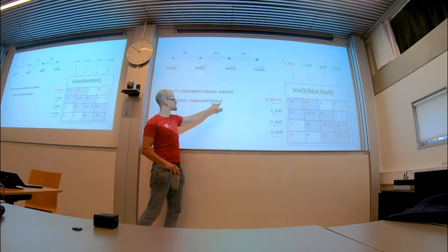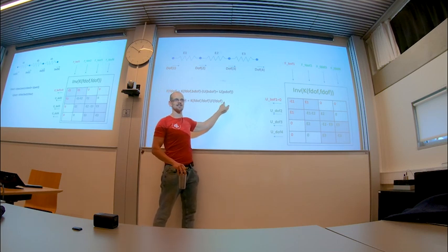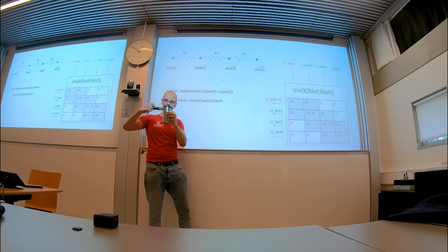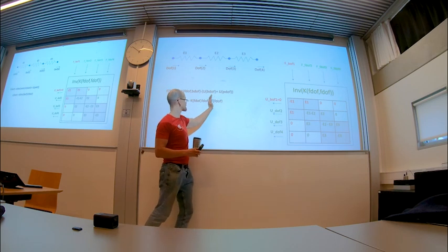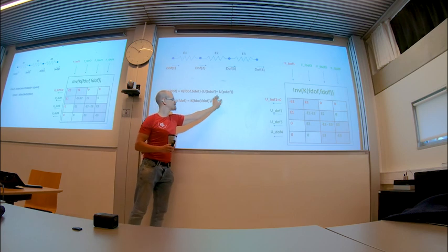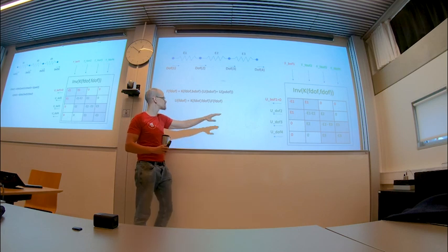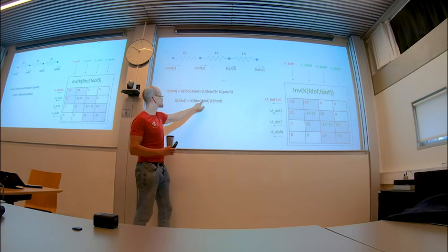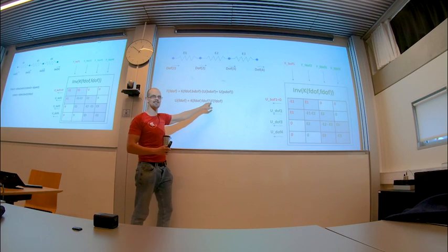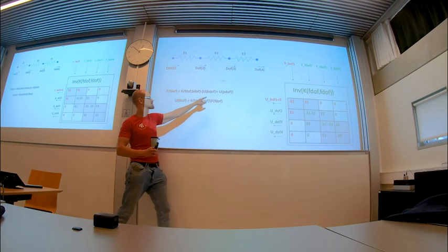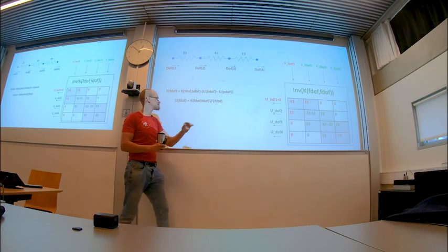And then once you have all the forces from the outside, you can also add forces of your own, external forces. It can be like a load on a specific node along the structure of a shaft. You add them here, there's a plus sign. And then, no matter how big the matrix is, million by million, I don't know how long it will compute, but you invert that, and this is a MATLAB command, automatically it finds the optimal algorithm. There are many different algorithms to invert a matrix. So you invert that, and you get the distribution of displacements from the displacement you applied, plus the forces you applied. This is magic, that's elastic.